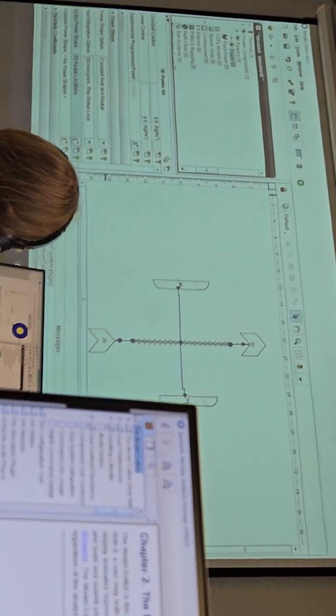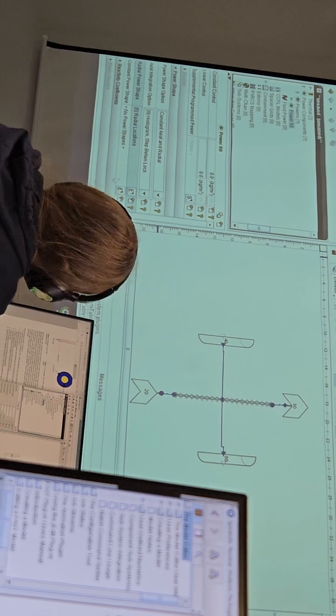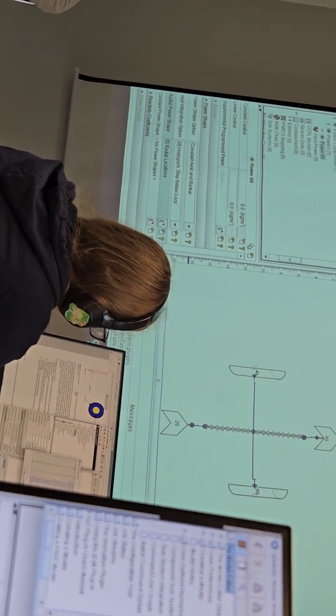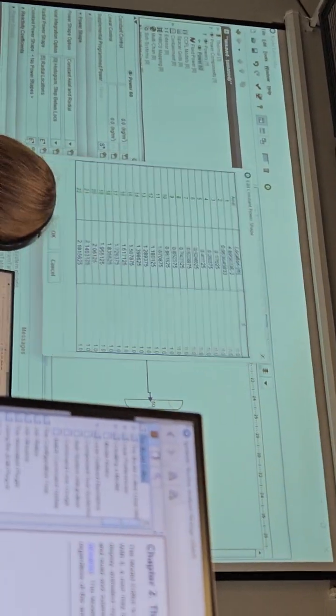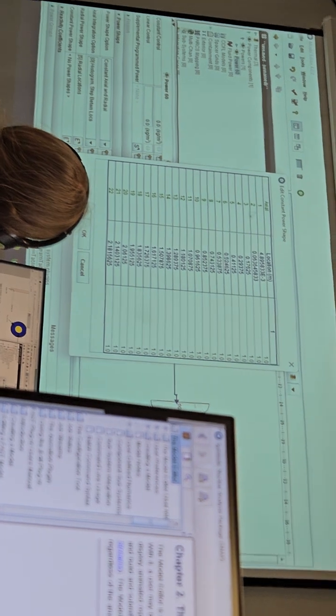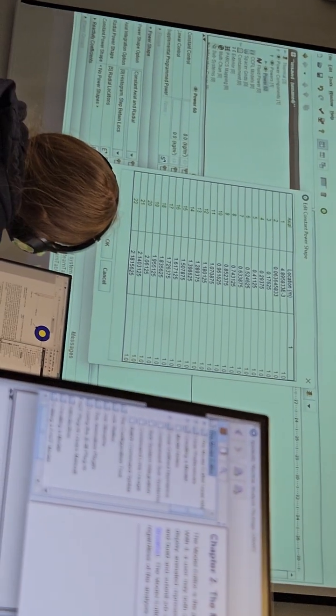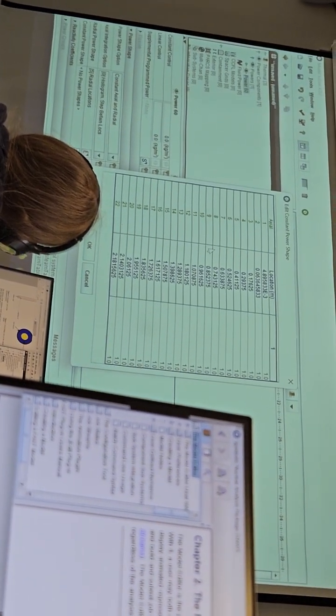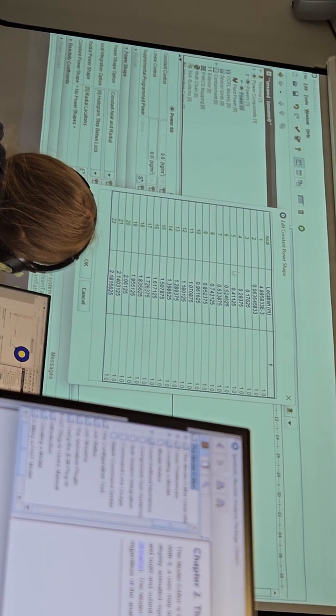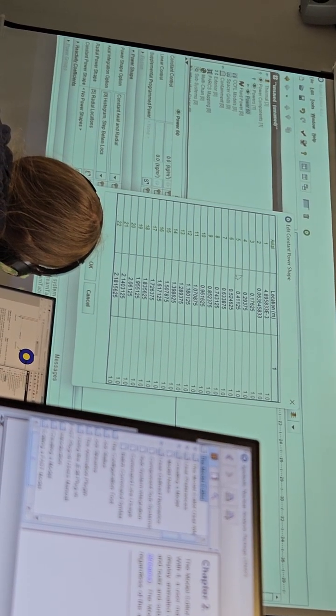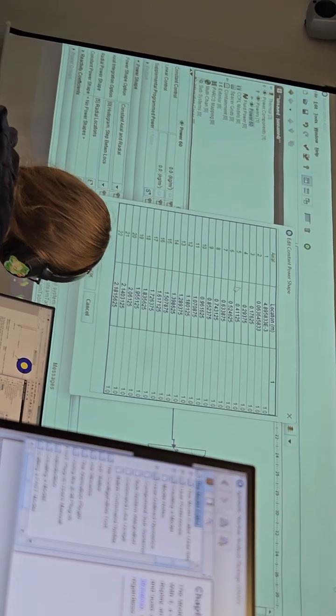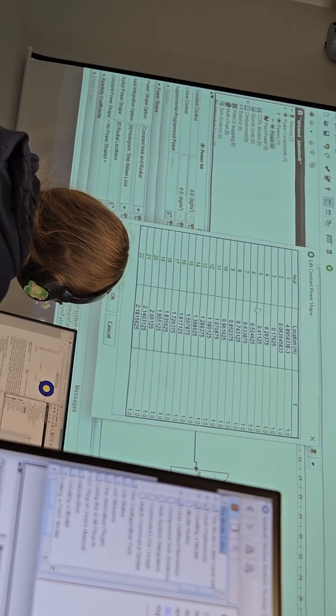And then to define the unheated fraction, we just need to go to the constant power shape. You will see the table. Here we will have 22 nodes. It is just because we define the option for the fine mesh reflood model.